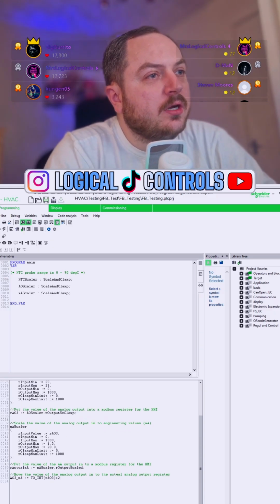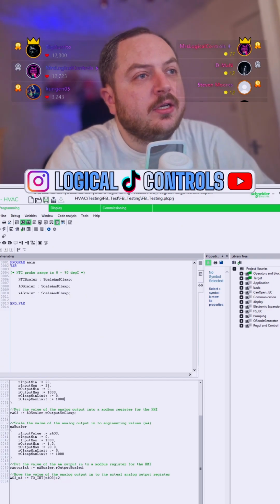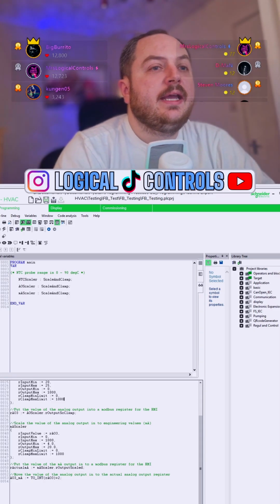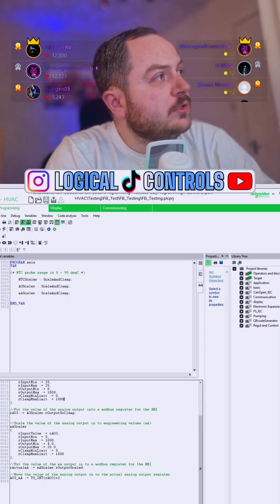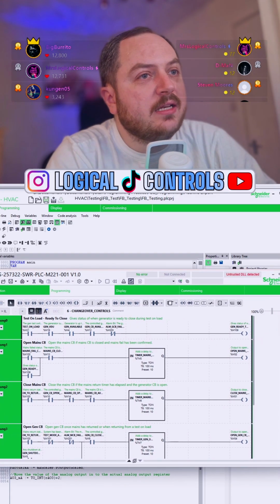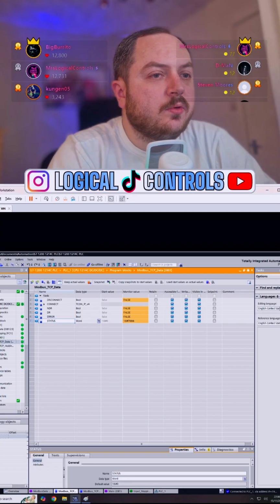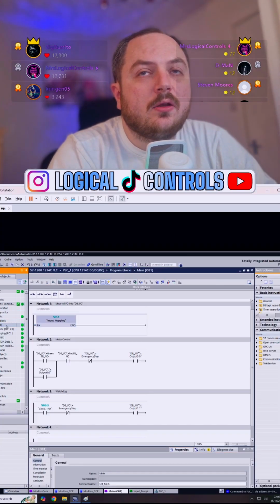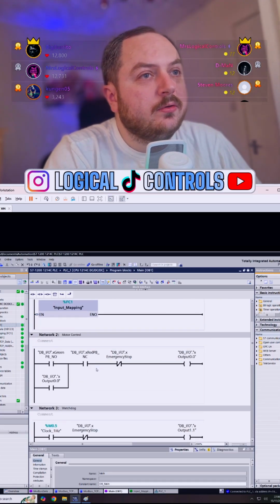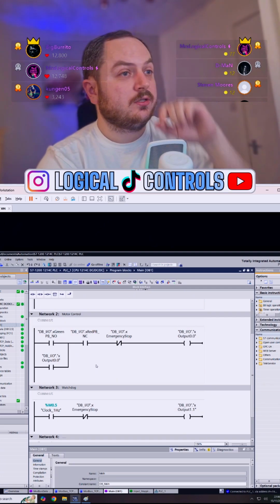Have you ever used Arduino? I have, yeah, Bennett. I've got a couple of videos showing OpenPLC, which is software you can use on an Arduino, so on a two-to-three pound microcontroller, to run ladder logic. Did I do any ladder logic in here? Yeah, so you can basically program an Arduino using ladder logic if you download OpenPLC. Totally free, doesn't cost a penny.